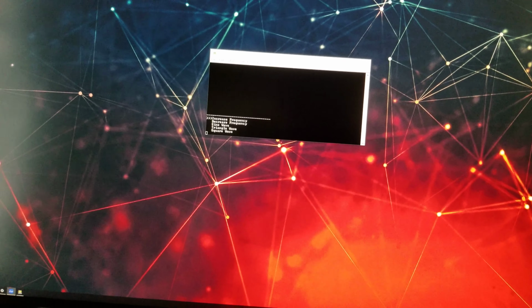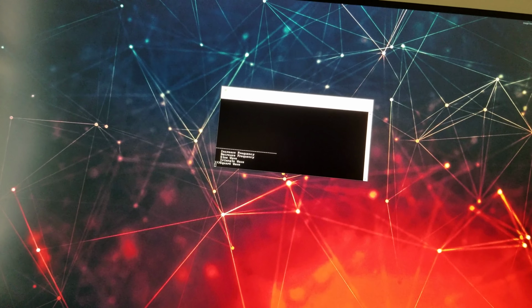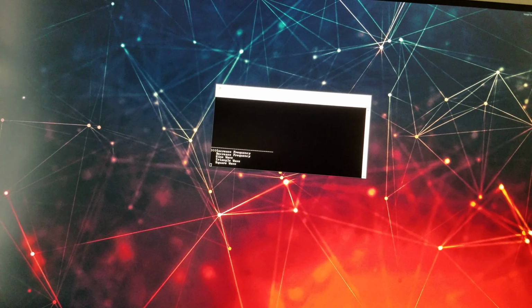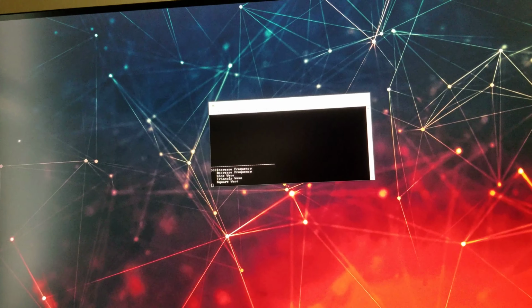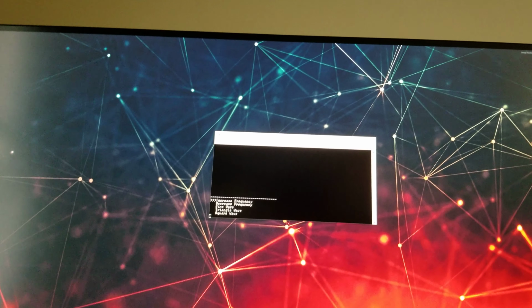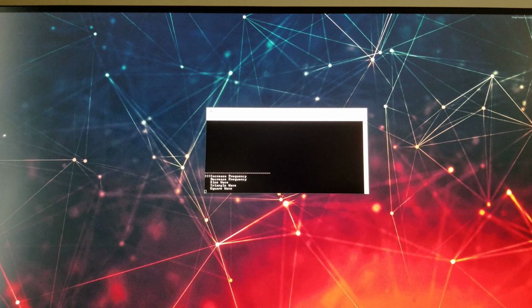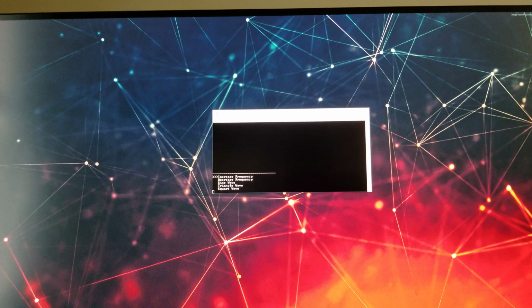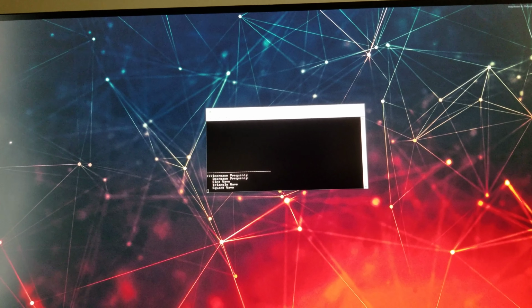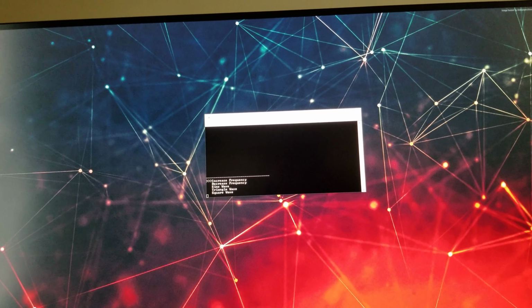And then obviously we have 3 different types of waves: the sine wave, triangle wave, and square wave. I also offered 2 commands for increasing and decreasing the frequency. I wanted to give the user better resolution on the control for the frequency, but it turns out with the prescaler, the formula for the frequency into the PWM timer is clock frequency divided by prescaler plus 1.